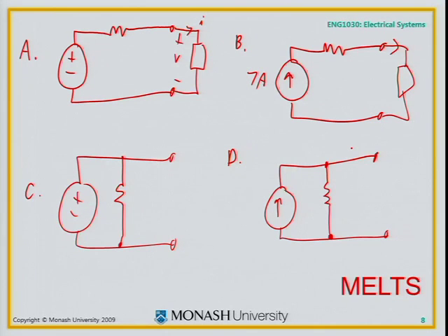On the VI curve, that's straight up. I equals 7 amps no matter what. There's nothing to give it a slope. The resistor is irrelevant in that circuit. Remember what a current source does. It pumps out that much current regardless of what it's connected to, the terminals. It does not work. Its VI characteristic is straight up like that. I equals 7 amps.